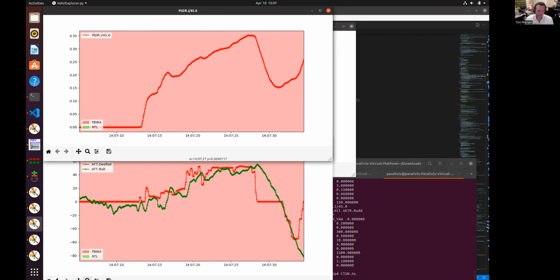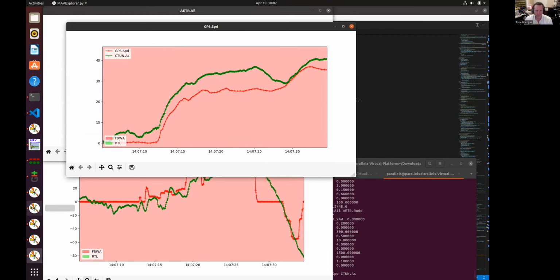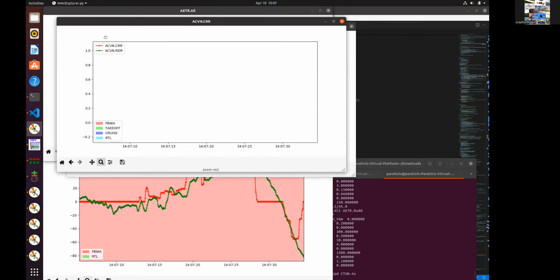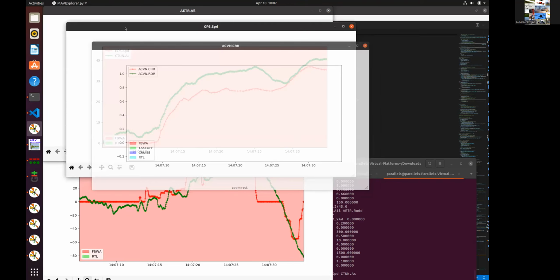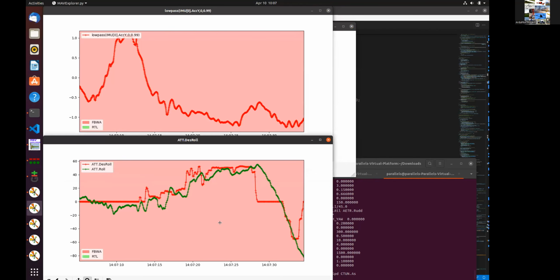We've certainly done it by accident a bunch, and it happens inadvertently all kinds of times. But it'd be nice to actually have a negative throttle that could feed into that somehow. We could have it as virtual flaps, because you could just add it onto the rudder and let the roll loop and the navigation controller compensate. So you could have that as an option of proportional flaps onto rudder.